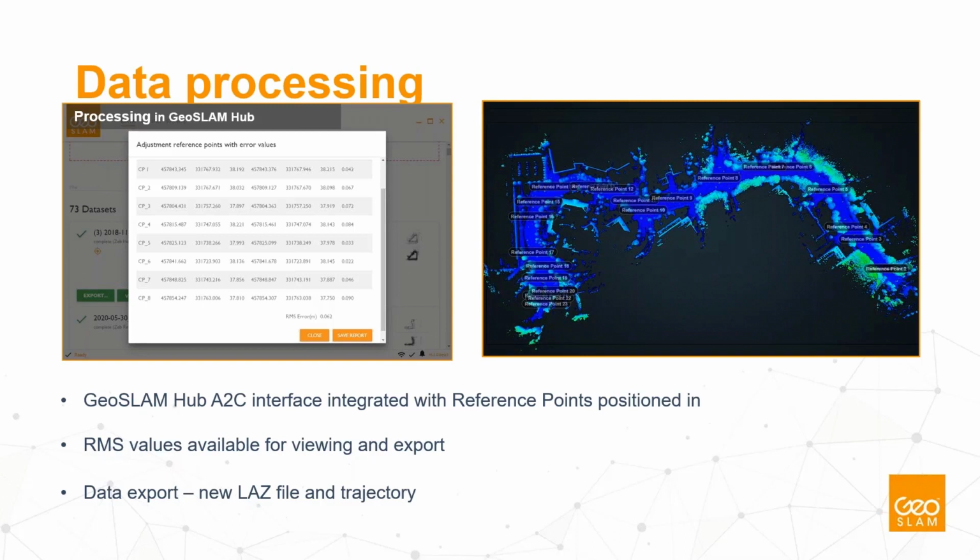I will stress that we should have the minimum amount of 4 control points in a single scan. A scan could be up to about 20 minutes long capture time, so you can walk around for 20 minutes. But along that, we should look to get at least 4 control points, and they should have a nice even spread around the scan area.